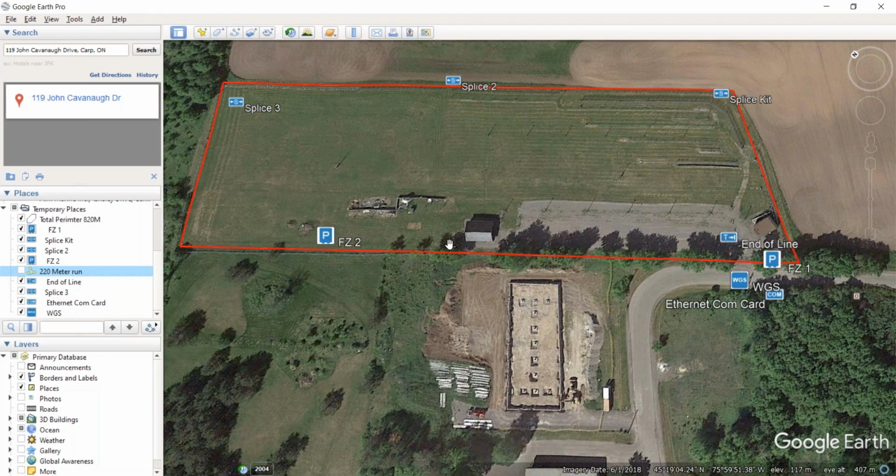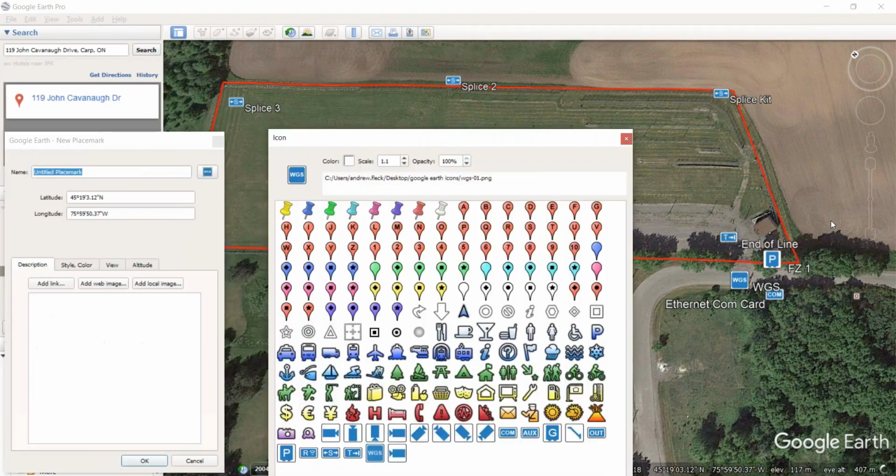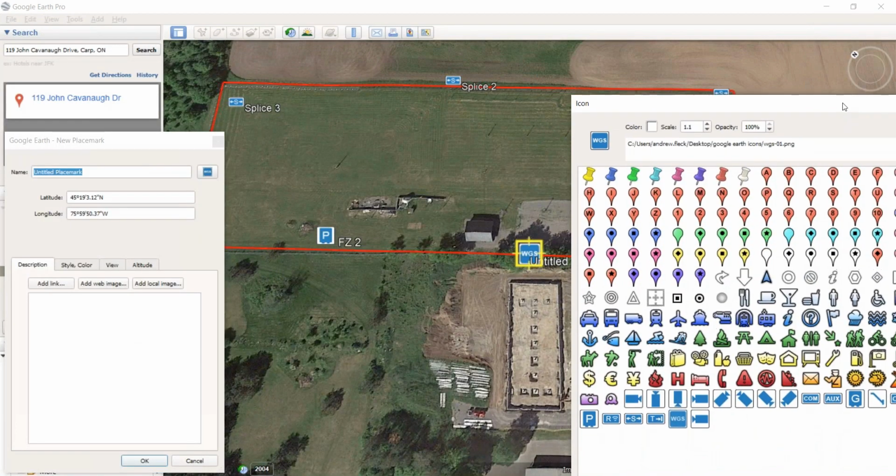Now, if I'm looking at just a copper flex zone system, I would say essentially I'm done. But most of the questions that come up now are what our camera coverages are going to look like, and what my zones are going to look like. Historically in Senstar, we try to run cable lengths that are aspects of a zone, and then we do what we call the crisscross effect for adding cameras. And as you can see here, I have a few different camera angles in place.